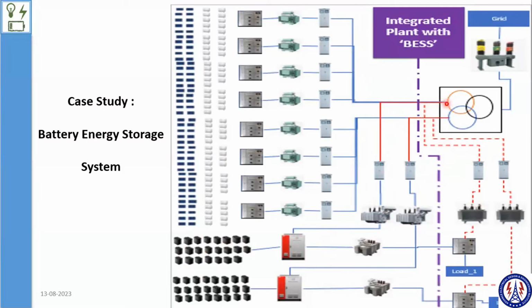You're again tapping here. Before connecting to this, there might be a yard, right? The isolation panels or isolation tower, right? You can isolate that. The switch yard would be there before the transformer. And then there are again separate VCBs, then tapping to this panel and then powering the load. See, now if you remember initially with the problem statement, what they state: the load is going to operate in the daytime from the grid as well as your solar plant, correct?